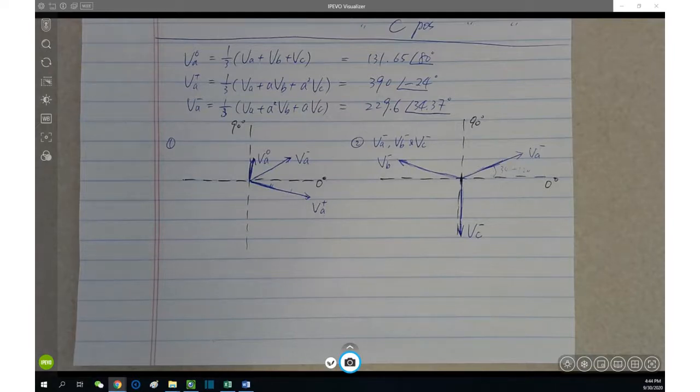Well, if the VA, VB, and VC minus magnitudes are getting closer and closer to equal, and the angles are each around 120 degree, that's when we'd be able to use the three-phase balanced equation for power, right? Correct. So if we were close to a three-phase sequence and wanted to be quick with a calculation, we could get a reasonable approximation by just using the three-phase balanced power.